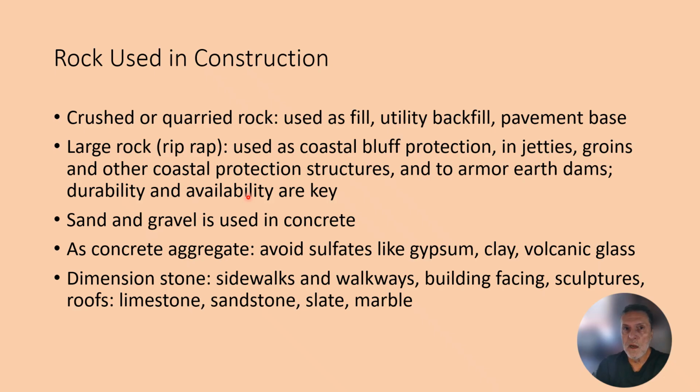Here in San Diego County, preferentially, we use the Santiago Peak Formation, which are metavolcanic rocks, very dense, very durable, very strong. We use sand and gravel and concrete. We want to avoid certain materials like gypsum and clay, which can weaken concrete aggregate. And we use rock as dimension stone to build special structures like sidewalks, facing, sculptures, etc. Okay.